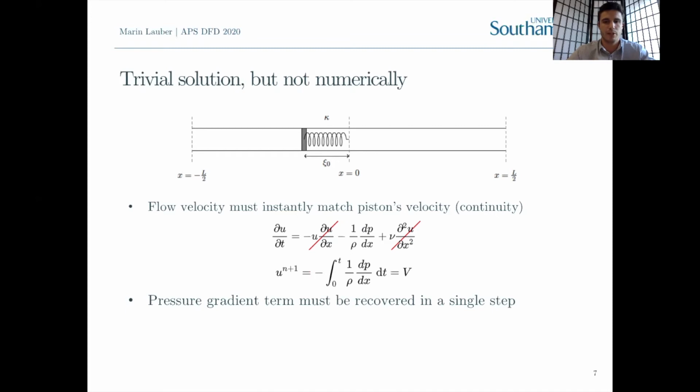So if you solve this numerically, it means that in a single step, when you solve for the pressure, the pressure gradient term must recover the correct pressure field to drive the flow to the correct velocity.